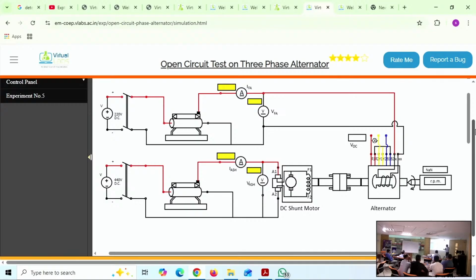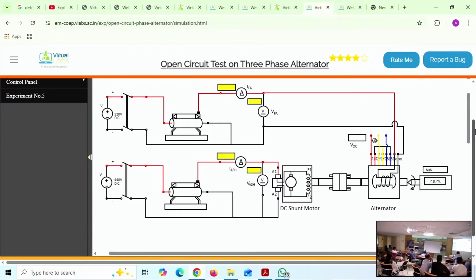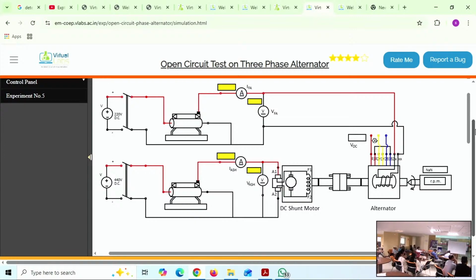That means the initial field current. Field current. We are controlling the current here, and we are talking about excitation, flux. Again, a student may get a doubt. We are giving current. We are changing everything. We are talking in terms of flux. How does flux come by the supply of current? Electromagnetic. It is electromagnetic, a magnetic field induced by electricity. That is how we are getting it. See, if it is a permanent magnet, we cannot vary this in this fashion.